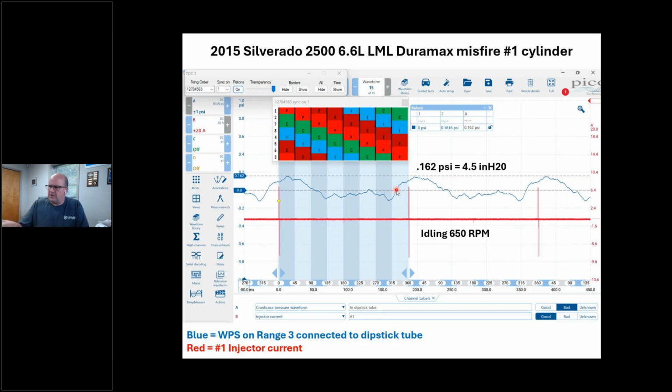If I can rule out things like this, like if this would have passed, like if I'd have rolled this thing over and I didn't have much crankcase pressure in this thing, no, I know I got a head problem. At that point, it's probably worth pulling the heads. But I'm not lifting the cap or pulling the engine or anything. I'm not pulling the head for this, agreed? Because I know the pan's got to come off, or it might have cylinder wall damage or whatever. Okay? I know this is a short block problem. That's all I know. And it's more than likely a piston because it's chipped up, hopped up, and all that stuff.